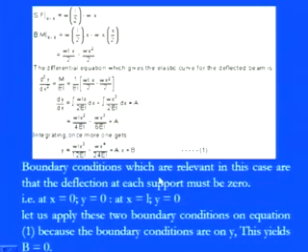For these sections again we need to calculate the shear force and the bending moment, but here the sign conventions are different, because the reaction from the simply supported beam at the extreme left corner is going in the upward direction, and the loading due to this UDL is coming in the downward direction.